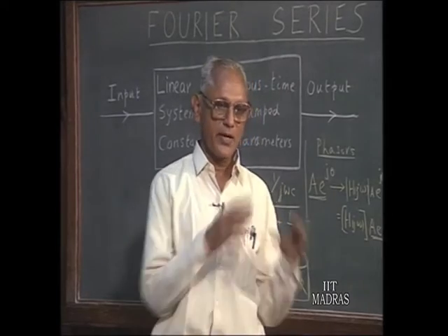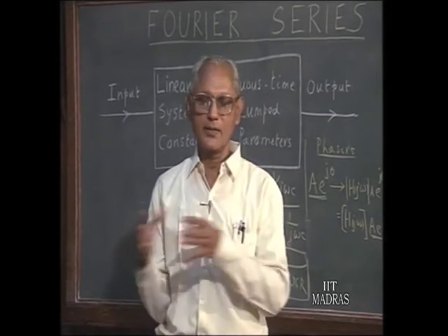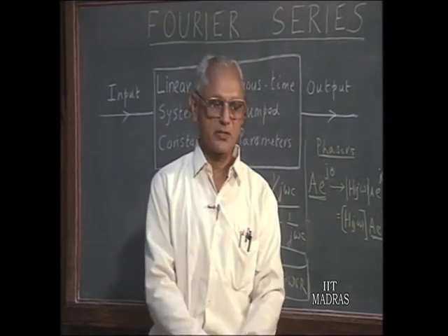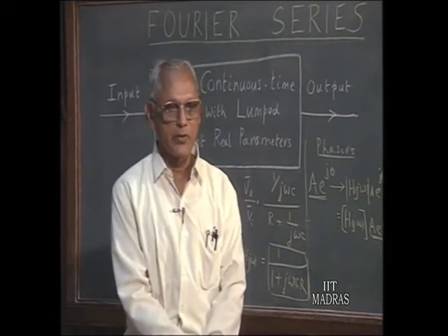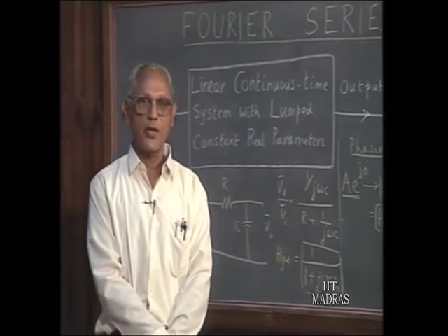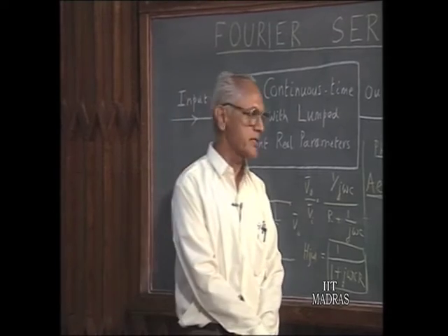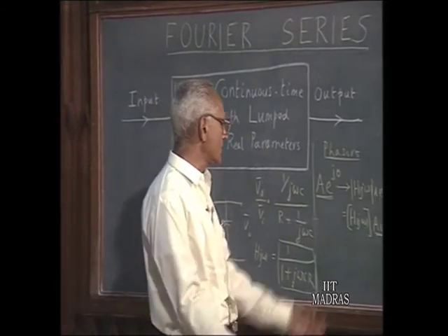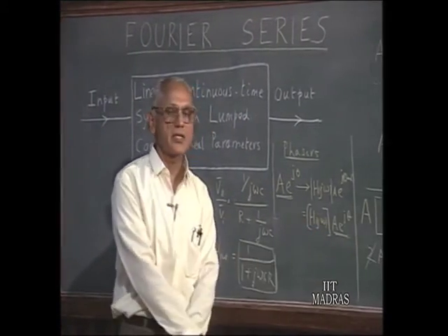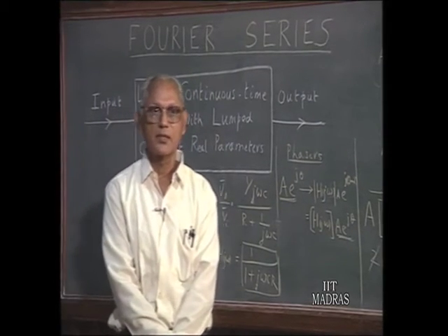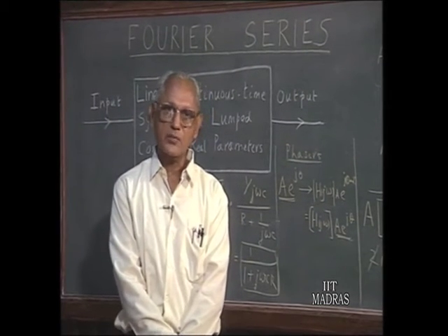You can find out the parameters of the input quantity and the output quantity using your instruments, maybe an oscilloscope, maybe a voltmeter, whatever you have, measure the output phase and output magnitude in relation to the input, and measure the system function H of j omega for different values of omega. This is very convenient for experimentation purposes.